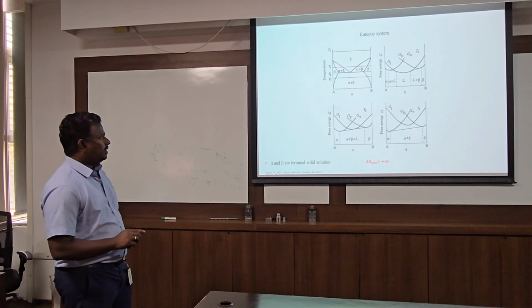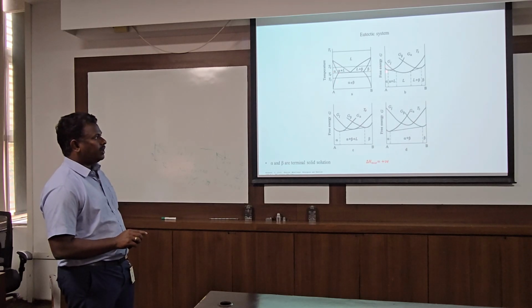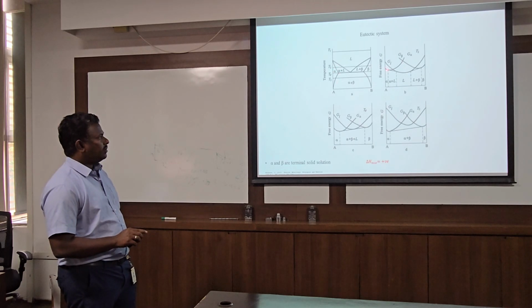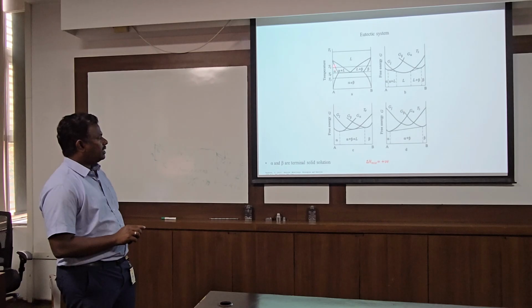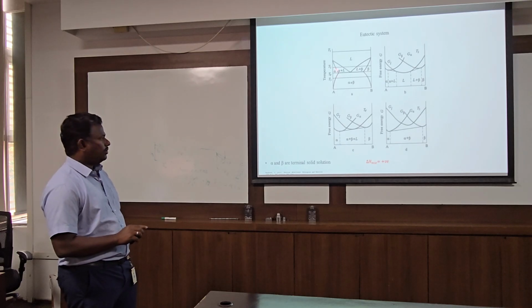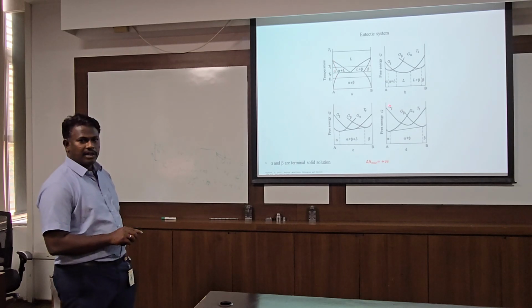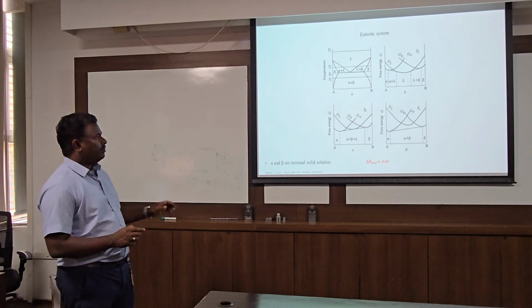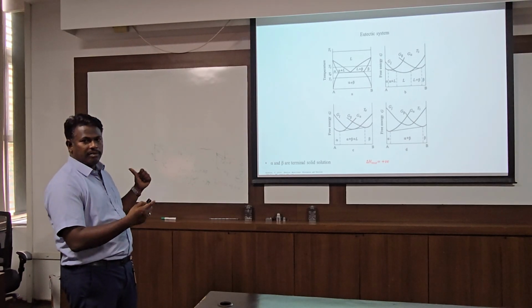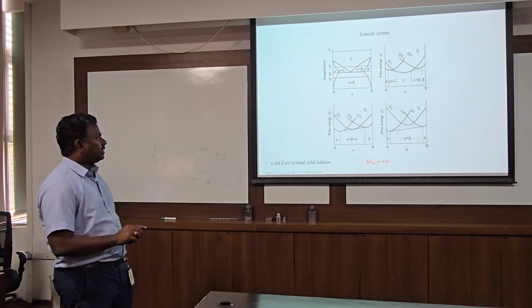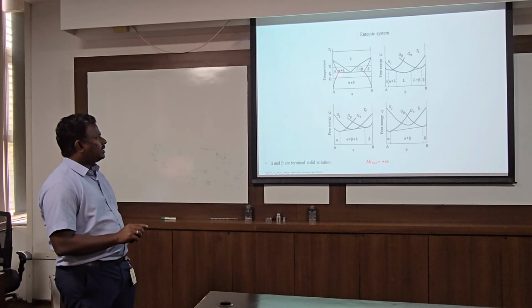The phase stability will be determined by the Gibbs free energy of the existing phases. Suppose I take T2. You see up to here, this is called the terminal solid solutions. Alpha and beta, they call it terminal solid solution. That means you have two terminals, and at the extreme ends we have this composition. So a phase alpha and beta stage like this.